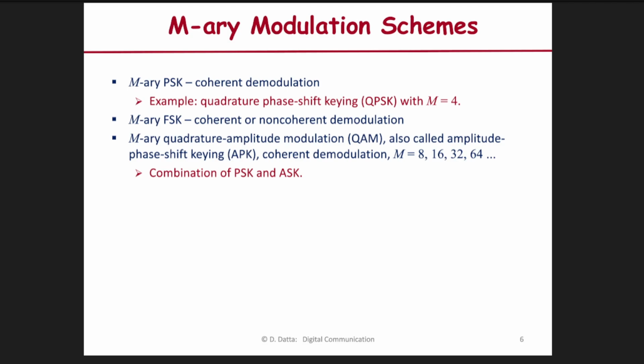So you know which one is coming. What you can do is divide into 2 branches, one branch tuned to f1, another branch tuned to f2. Then once you get f1, cos omega 1t, you can do similar things as you have done in PSK, or you can do it as in ASK, like ASK is envelope detection. So we'll go to that in detail later on.